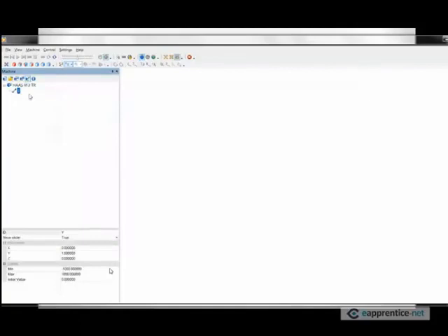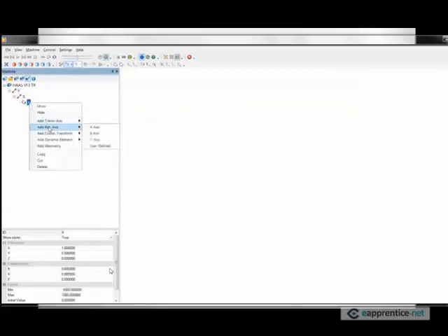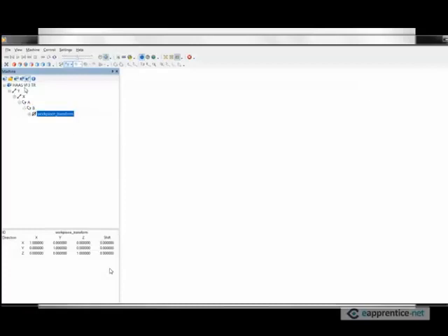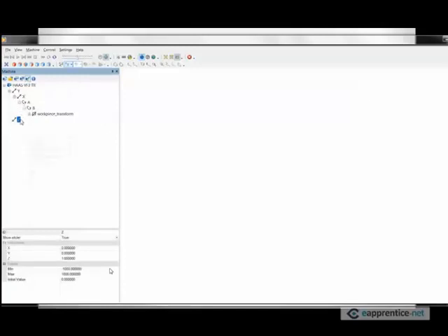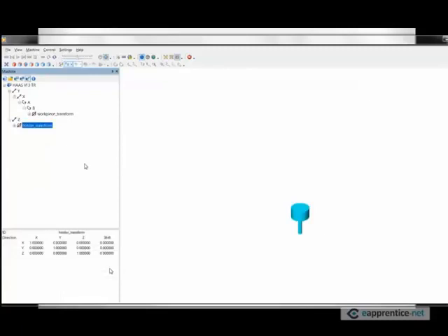Next thing we want to do is add the y-axis. We're referring to our sketch. Y is carrying X, X is carrying A-axis, A-axis is carrying the B-axis here, and then we have this dynamic element called workpiece transform or workpiece set. On the next branch, we have Z-axis attached to the base, and then it's carrying the holder.